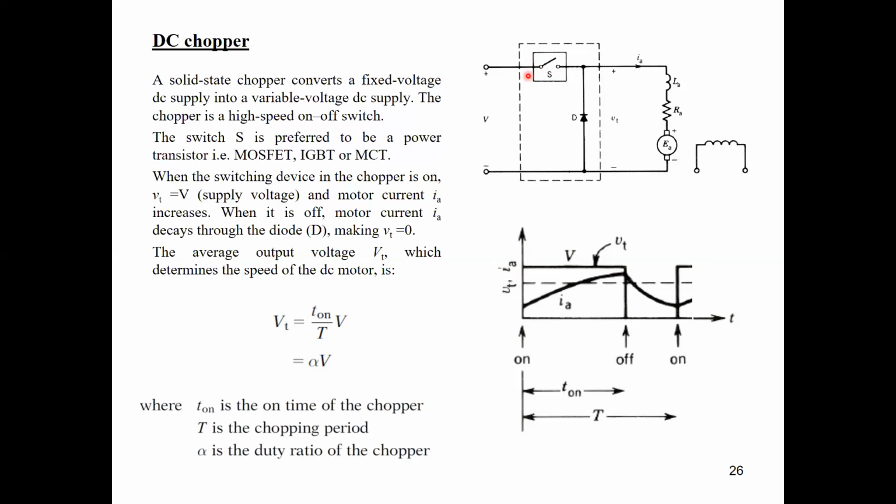For instance, for a DC chopper, we can increase the switching frequency, which means turning this switch on and off, up to 50 kilohertz. However, the maximum frequency in thyristors is 400 hertz only. So this will make a very smooth output voltage for the DC motors, which reduces the ripples and makes the output voltage and current of much higher power quality. Right.